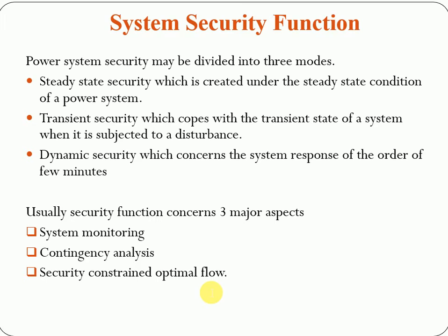The continuous updating information on the condition of the power system is given to the operator through system monitoring. Based on this, quantities such as voltage, current, and power flow, and the status of electrical equipment such as circuit breakers and switches in every substation in a power system transmission network can be measured and monitored. In addition, further information on frequency, generator unit output, and transformer tap position can also be gathered and transmitted back to the control center.